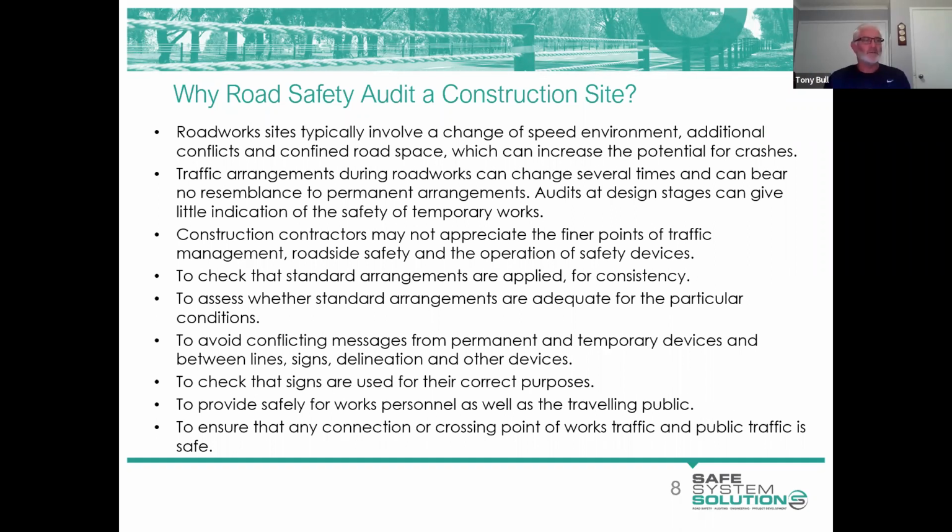Make sure that signs are used for their correct purposes. You so often see the prepare to stop sign. It should be used in association with portable traffic signals or a traffic controller with the stop slow bat. That's when that should be used. It shouldn't be used with roadwork ahead alone, prepare to stop. You can have it with roadwork ahead, but you must make sure you've got that symbolic traffic controller or the traffic signals with prepare to stop.